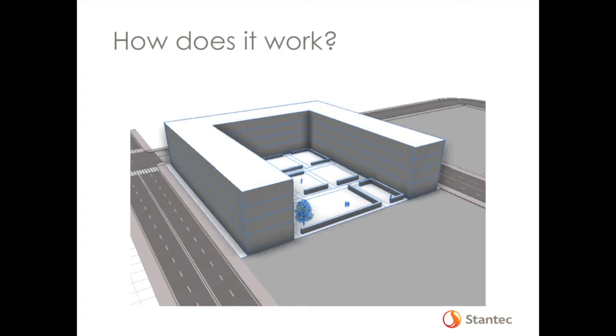From the parceling side, we can add, say, a building geometry rule. Again, drag a rule to a parcel, and now it's going to start generating some sort of geometry based on the defaults for the rule. It's going to create this U-shaped building, with landscaping, trees and people in the middle. It's just all defaults of how the rule is based. But the nice thing is that it's highly customizable after the fact. It looks a little overwhelming, but this is actually just all slider bars or entry bars for things you actually want to enter in there.